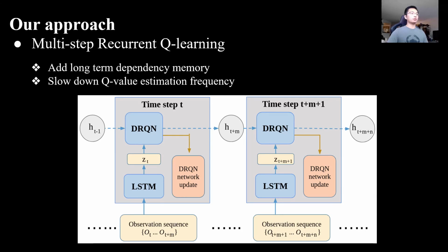So, in our approach, we used a longer observation sequence as input. When the tactile feedback is weak, the agent will not make a decision on the actions, but stick to the current action. Once there is a strong feedback, the agent will make a new decision based on the observation sequence. Also, since the input sequence length is not fixed, we use an LSTM layer to process the input so that the decision module gets a fixed length vector z.